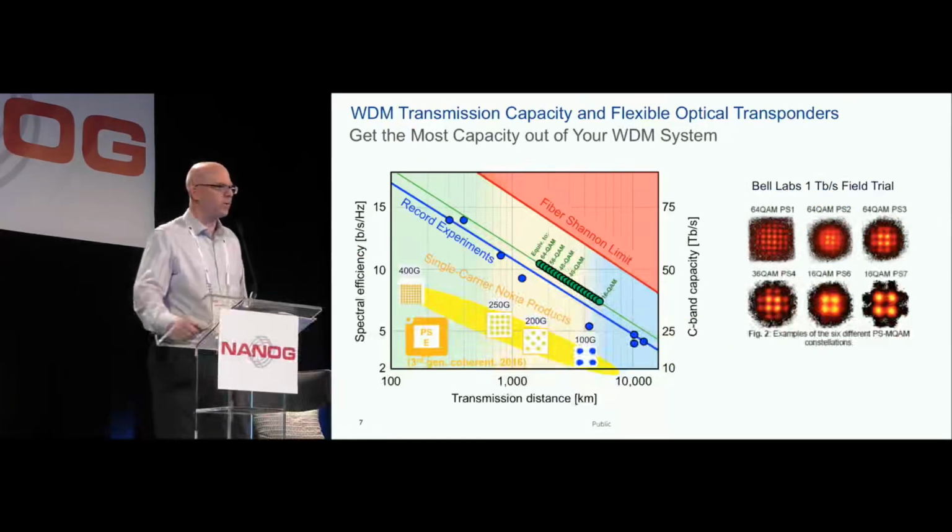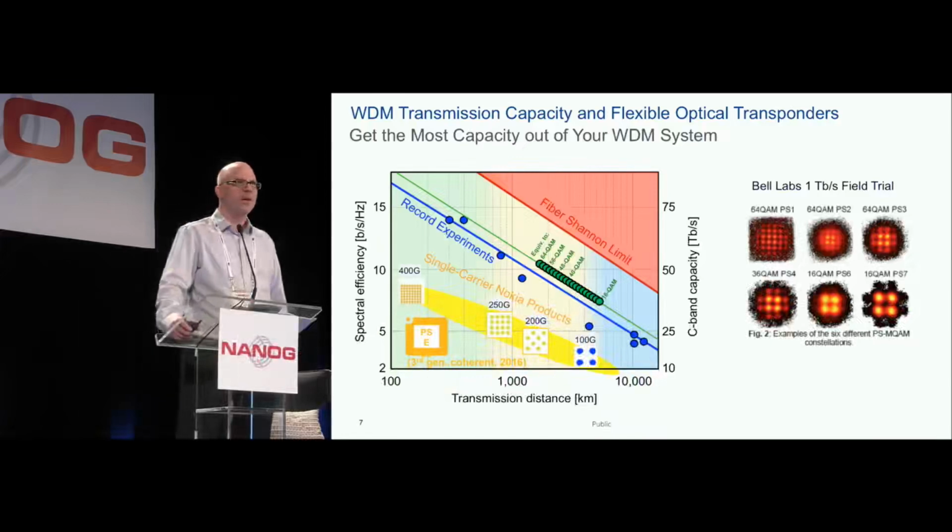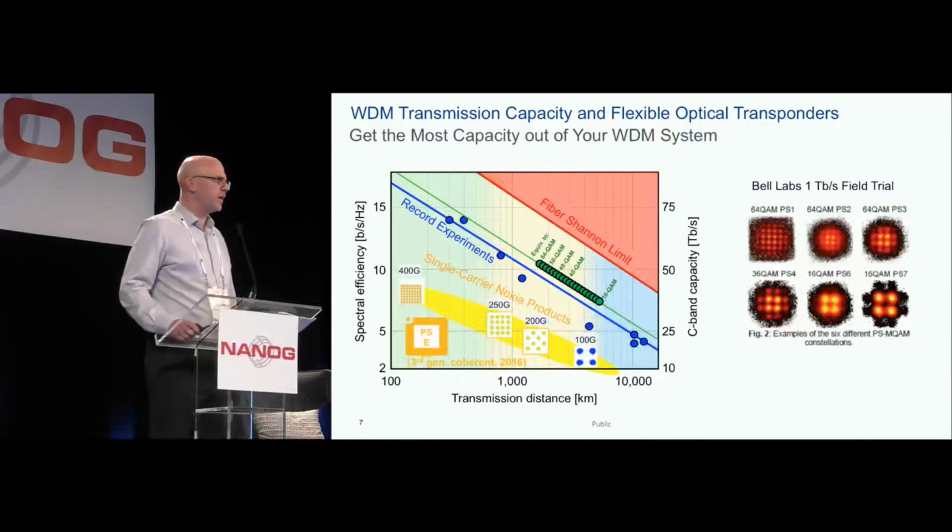So in the end, what do we want to do? We want to get the most capacity out of our WDM system as possible. And we're in this interesting situation now with optical networks where we're approaching the fundamental limits of single mode, single channel, fiber capacity.